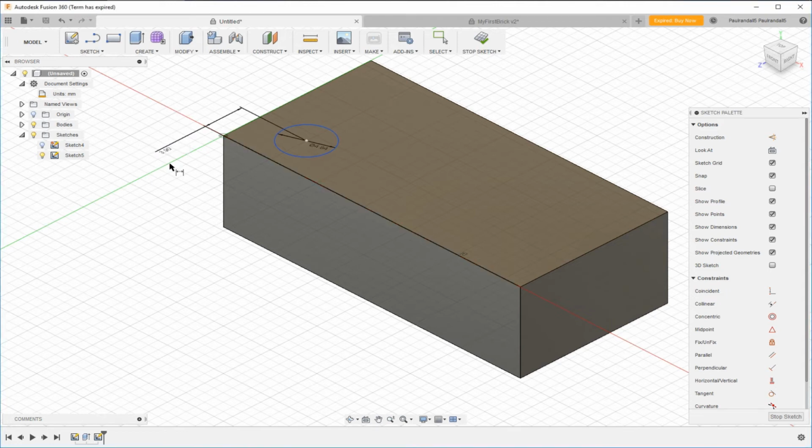And we're going to just type in 3.90, and you don't have to put in millimeters, it presumes that. You'll see that the dimension tool is still active, so we can select the center again and select this edge, and we'll have our dimension in this direction, and again put 3.90 and press enter. And that correctly positions the outliner peg.